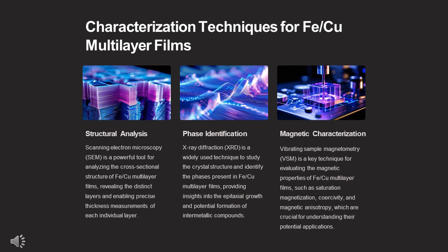Characterization techniques for ferrum and copper multilayer films. Magnetic characterization. Vibrating sample magnetometry (VSM) is a key technique for evaluating the magnetic properties of ferrum and copper multilayer films, such as saturation magnetization, coercivity, and magnetic anisotropy, which are crucial for understanding their potential applications.